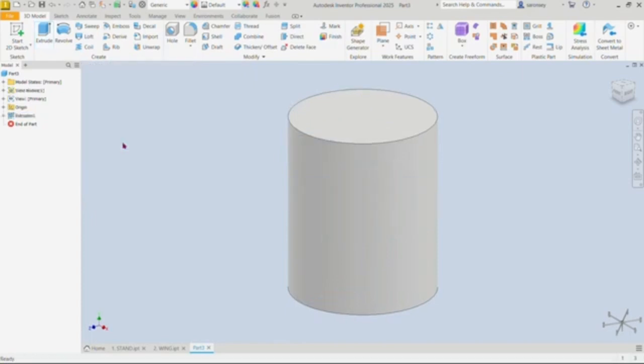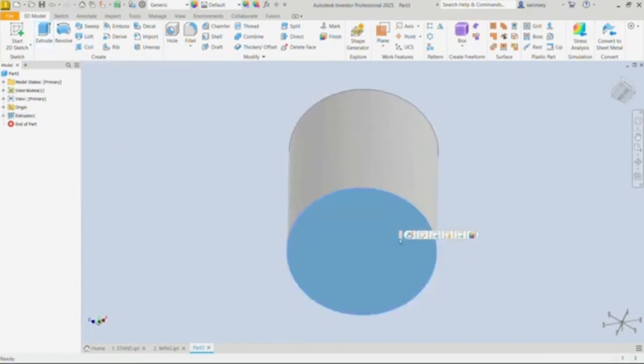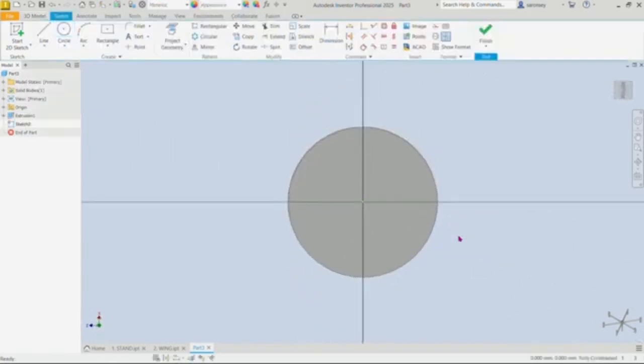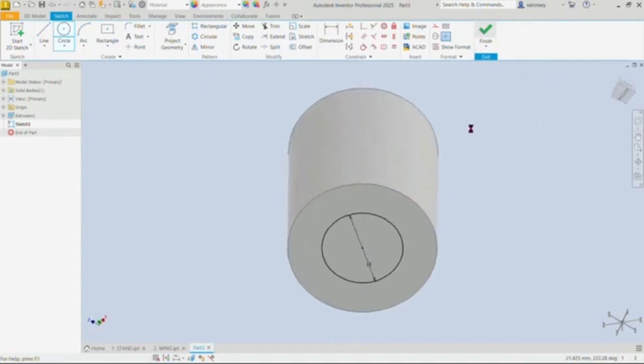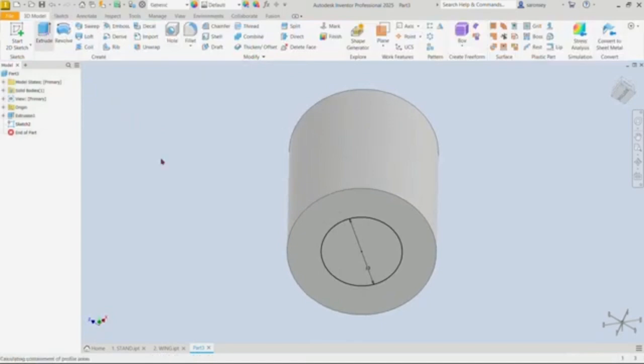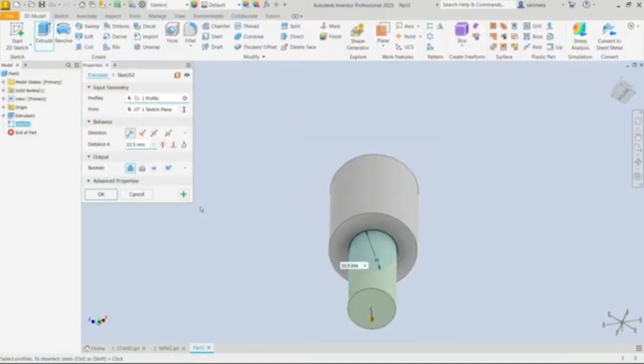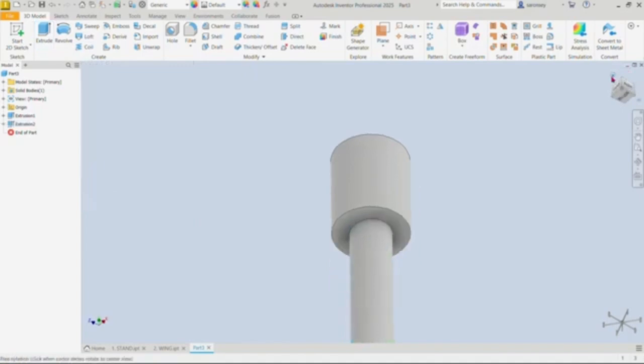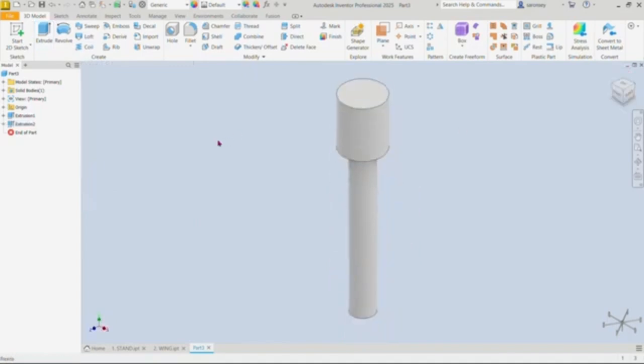Let's enter that. Now let's turn this around, and then on this face we would create a sketch on it. Let's pick the circle command a second time, and from the origin draw a circle of diameter 10 and enter. We would also finish this, and then we can extrude. So the extrude command, the profile has been selected, but the distance of extrusion is already changed to 70, and okay, let me get the isometric view. Next, let's look for a plane to work on to draw those rods on which the wings will be mounted.